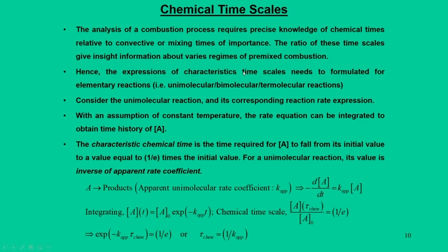That means if your chemical time scale is in milliseconds, your mixing time should be of a similar duration, so that we can ensure maximum fuel is burnt. So, precise knowledge of the chemical time scale is very vital. For that purpose, we need to formulate expressions for the characteristic time scale for the elementary reactions, that is, unimolecular, bimolecular and termolecular reactions.